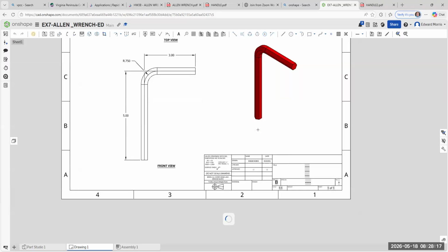I'll do a paste again here. Double click, and you can just edit it to ISO VIEW. Now, I can't overemphasize enough the importance of making sure all your letters on your drawing are capital letters, uppercase letters.